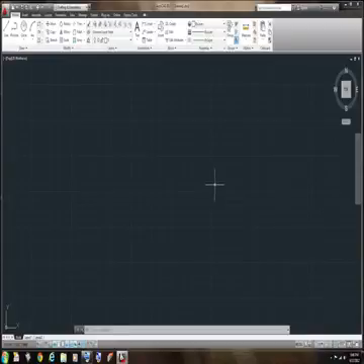If you're drawing for a construction company and you're drawing a house, with inches and feet, you should draw at 6 feet 6 inches, and so on and so forth. If you're drawing for a mechanical company or an aerospace company, and you're drawing in millimeters or something like that, you should draw at that scale. So in AutoCAD you always draw at actual scale. Let's go ahead and show you the different features of AutoCAD and how you interact with those features.